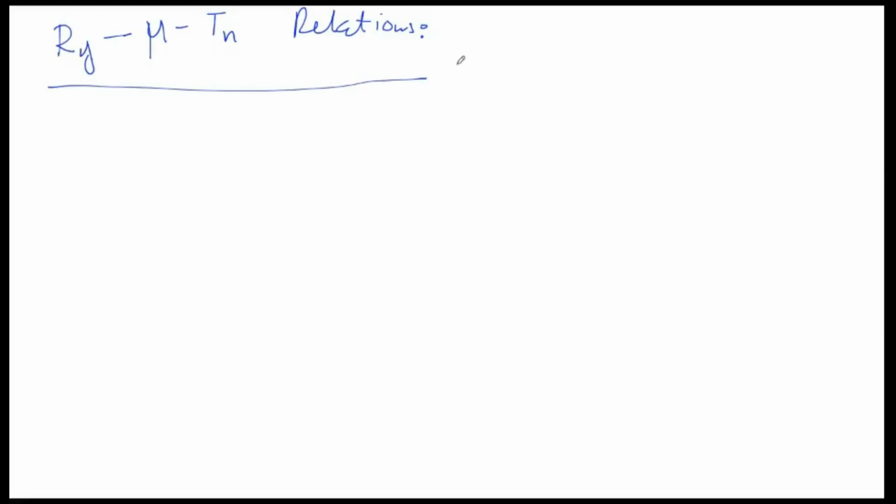We know that the Fy for which we make a design is always less than the minimum strength necessary for the structure to remain elastic. So we all know that Fy is always less than Fo, and that's why the system behaves inelastically. And by this we mean that Ry is greater than 1. If Ry is 1, the strength reduction factor is 1 and the system will behave elastically. But when Ry is more than 1, the system will behave inelastically.